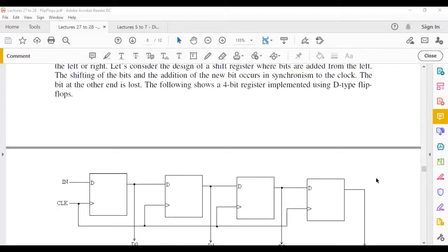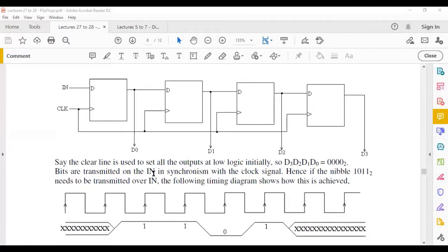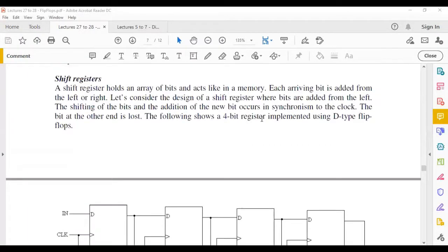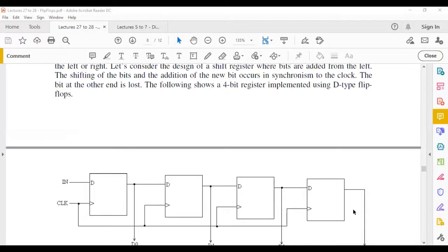So this is called a shift register. You are shifting the bits in turn. So ultimately, when all the bits have been transmitted, you have recovered your original data, and then you can act on it. So I hope it's clear how this is working. If you want to have a 4-bit shift register, you're going to use 4 D flip-flops connected in this fashion. If you want to have 8 bits, you will have 8 connected like this, so you can extend it.